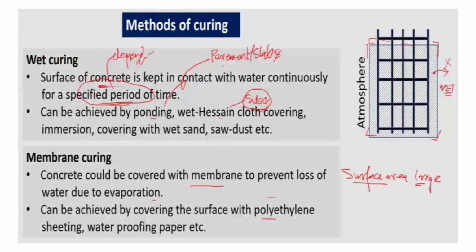So here the concrete surface is kept in contact with water continuously for a particular amount of time. This can be achieved by ponding, wet hessian cloth covering, immersion, covering with wet sand, sawdust, etc. This is mainly done in most of the cases in India especially.